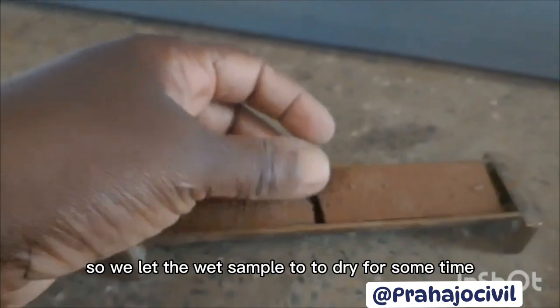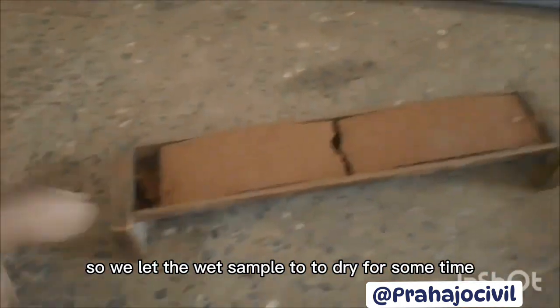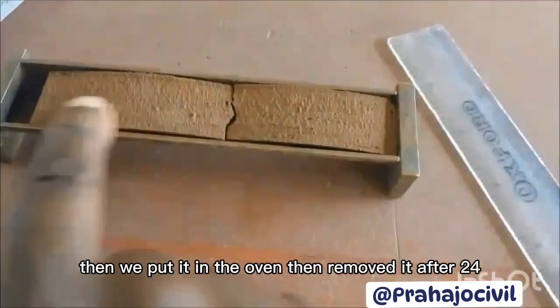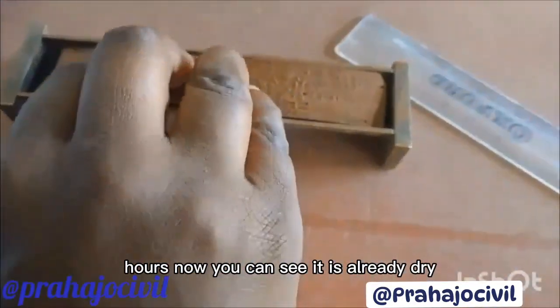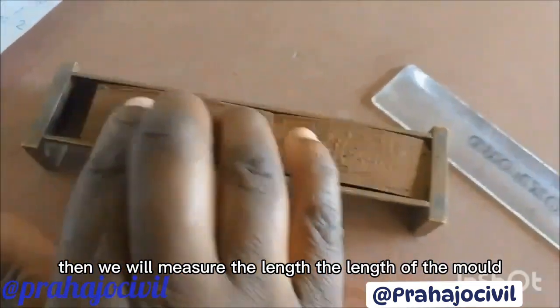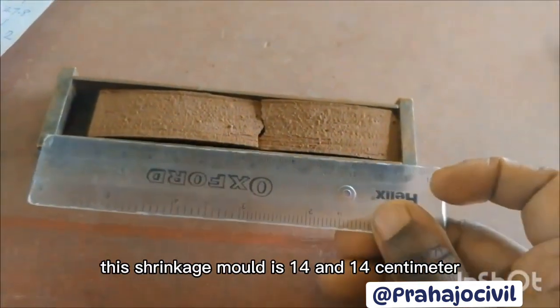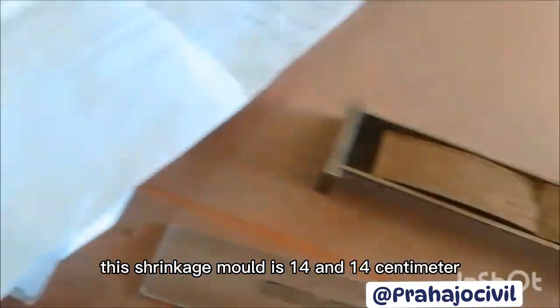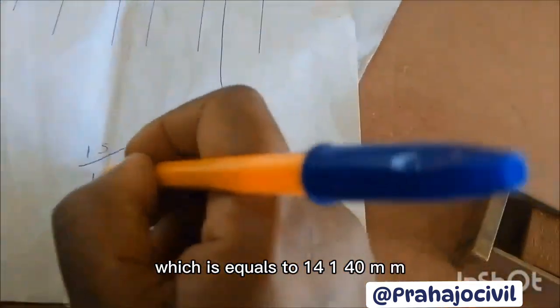So we let the wet sample dry for some time, then we put it in the oven, then removed it after 24 hours. Now you can see it is already dry. Then we will measure the length. The length of the mold, this shrinkage mold, is 14 centimeter, which is equal to 140 mm.